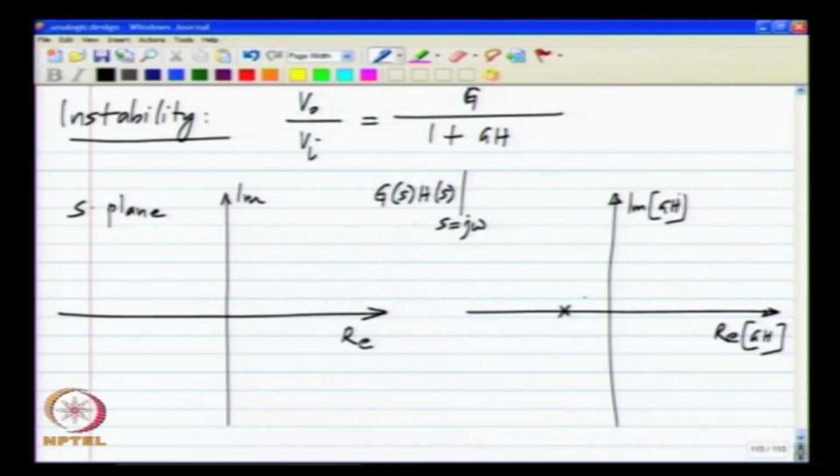Like I said rather vaguely, stability criteria involve avoiding the loop gain being minus 1. So, this minus 1, 0 is a critical point in this whole technique, and what the Nyquist criterion states is that the plot of the imaginary part of the loop gain versus the real part of the loop gain should not encircle minus 1 comma 0. That is, the plot can be something like this, okay.